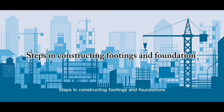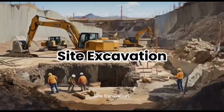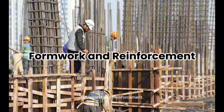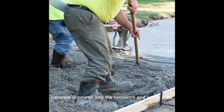Steps in constructing footings and foundations. Site preparations. Clearing the site and conducting soil tests. Site excavation. Digging trenches or pits to the required depth. Formwork and reinforcement. Setting up the mold and placing steel reinforcement bars to ensure strength. Concrete pouring. Concrete is poured into the formwork and left to cure, ensuring it achieves sufficient strength.